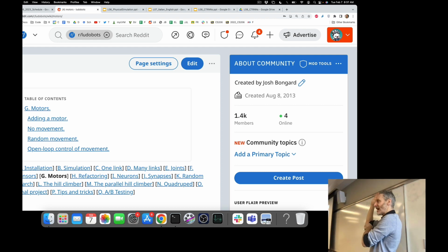So if I send a desired position of 90 degrees, I want to extend my lower arm out to 90 degrees. I might have that desired angle, but then I might ask for a desired angle of minus 80 degrees. I'm going to start flexing my arm in, back and forth, back and forth. Yeah? That's open loop control. We're telling the motor what the desired angle is. It's not coming from the sensors.